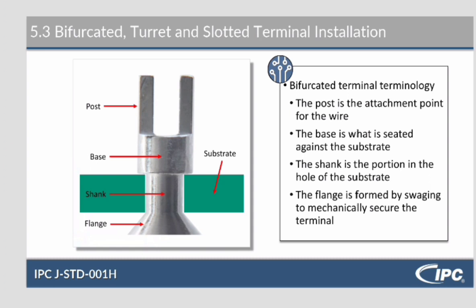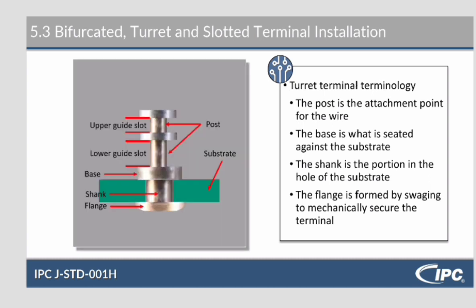When we solder these in class, we just solder the terminals. We don't do any kind of board installation, so you don't have to worry about all that. So I'll actually go through that part. It does talk about that a little bit in this module. I'll kind of skim over that a little bit. This is a turret. So again, you want to rest your wire against the base and wrap it around the post.